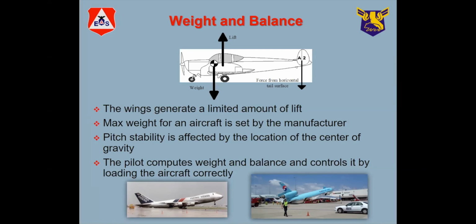With the illustration that's up here, if you put too much weight in the back, the tail of the airplane is going to be down low, just like these jets that are depicted here. If you put too much weight in the front, the opposite happens. So to make sure that everything works properly, we need to make sure that we have our weight of the engine and the instruments and all that at one point, and then everything else at another point, and they have to balance out, just like a balance scale in chemistry when you were in high school or what have you.